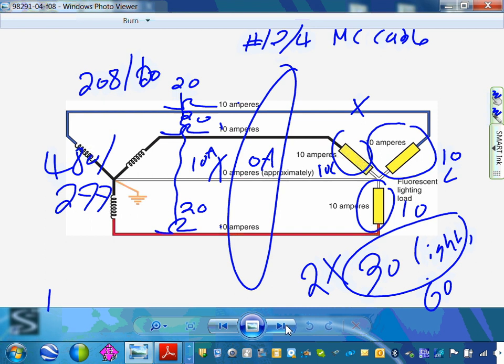Now, if you size based on LEDs, do me a favor. If your lights are LEDs, times this by 2 again. 120 coming out of which cable? That cable, you're looking at it. 120 light fixtures coming out of this cable, if they're LEDs. Why LEDs? Because LEDs, guys, barely draw half an amp each, 0.5 of an amp, to light. They don't draw a whole lot. That will give you guys a gravity.